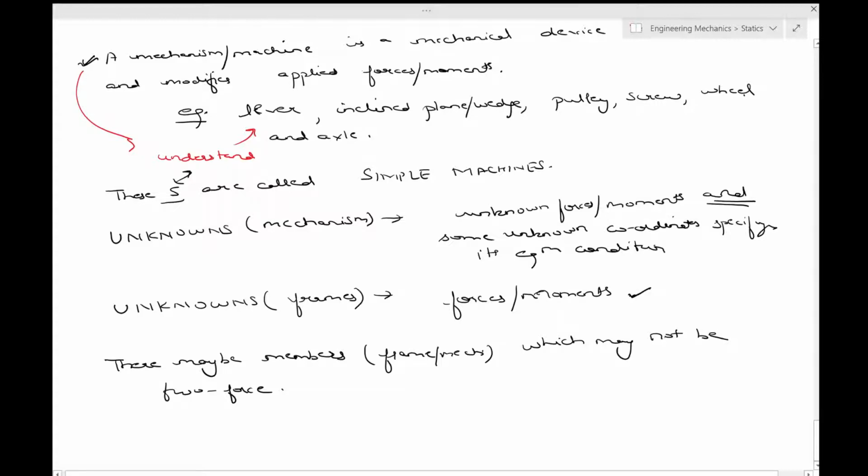so how you approach a situation, I mean, to solve a problem or a physical situation of frames and mechanisms depends on a case to case basis. So there is no general method how to go about it. Okay, and you have to, for example, out of the whole given system, choose subsystems and write the respective equilibrium equations for that.